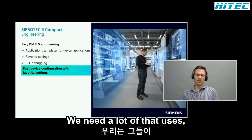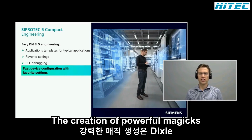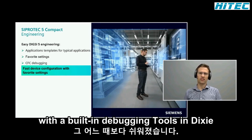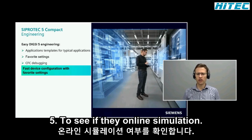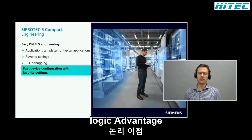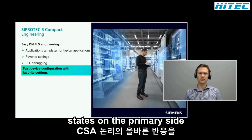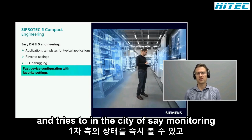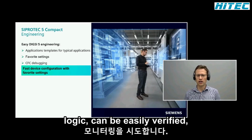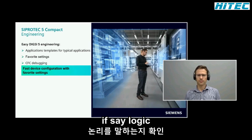We know that a lot of our users like the possibilities that our CFC Logic Editor offers. With the SIPROTEC 5 Compact, the creation of powerful logics is easier than ever before, with the built-in debugging tools in DIGSI5. The CFC online simulation helps you to test and troubleshoot your custom-built logic. The advantage here is that signals from the field are acquired in real time, and that way any changes or different states on the primary side can be immediately viewed and traced in the CFC monitoring so that the correct reaction of the CFC logic can be easily verified. This increases the safety and security of your own CFC logic.